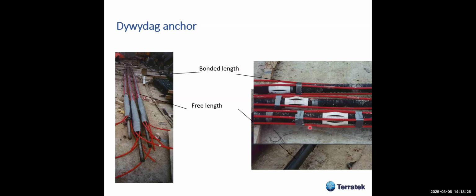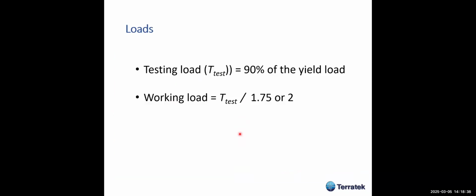Here's the centralizer, and in the free length, we substitute the grout with grease, as I'm going to show you in these anchors.